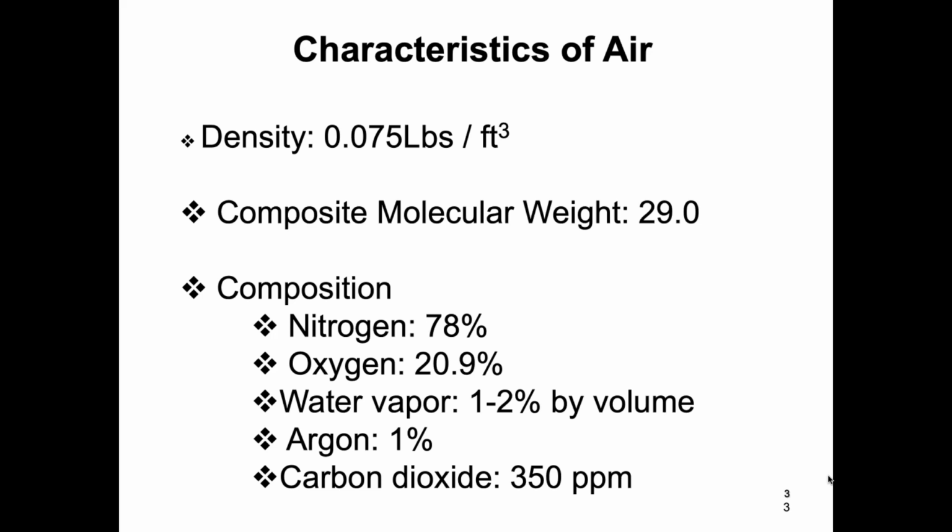That negative pressure is basically a kind of potential energy. In order to get air to move, you have to have a difference in pressure. So if we connect that to ductwork, we can run that ductwork to another area. Since we have a negative pressure at that point, that negative pressure can induce airflow through that ductwork. So some of that negative pressure becomes converted to kinetic energy, to do actual movement of the air.